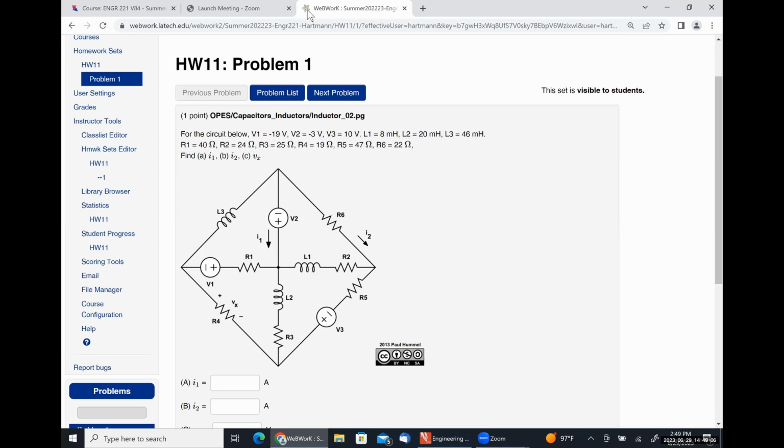So the values of the inductors literally do not matter at all. Because this is a DC circuit, simply treat every inductance like a short circuit and move on with your life. So this one looks scary, but really isn't anything remotely new.